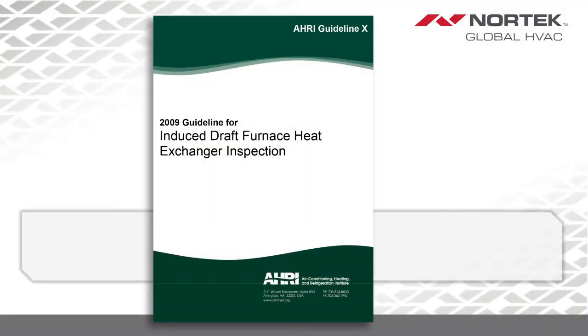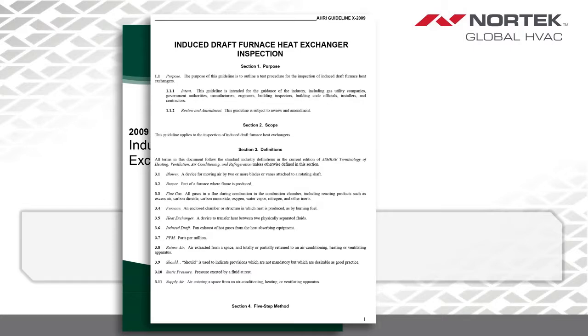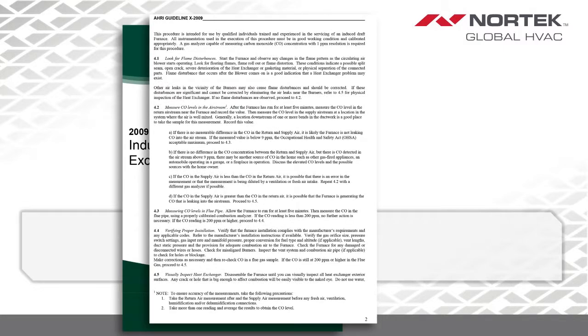Again, the fundamental of the AHRI test is an analysis starting in the flue pipe, and generally you're talking about operating the furnace for at least 5+ minutes. You're looking for flue pipe parts per million numbers exceeding 200 parts per million, and that's where it starts. Again, we'll try to provide a link for it or put that into an FAQ on our website.